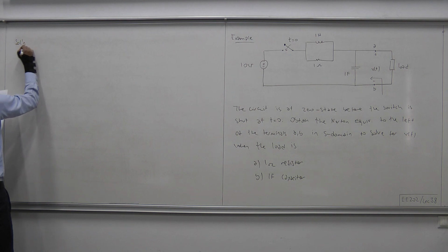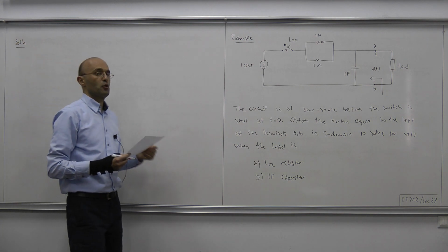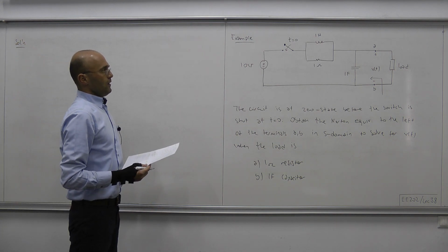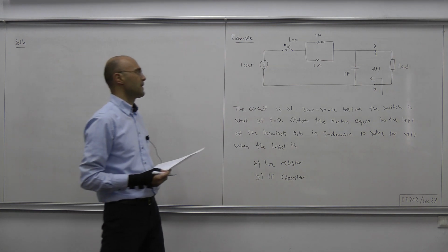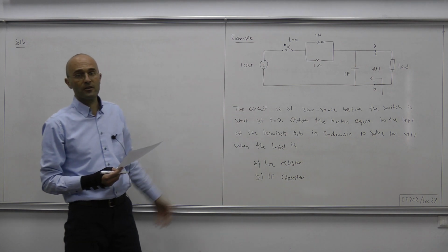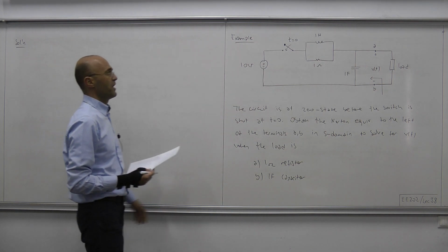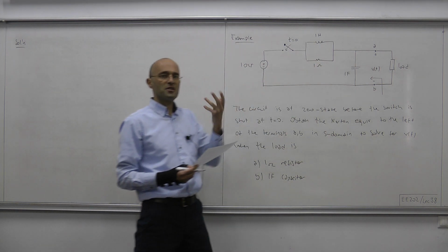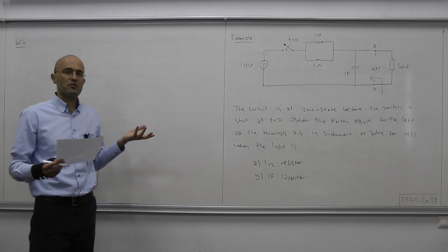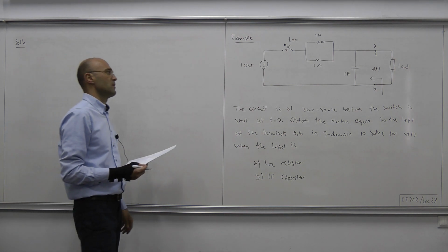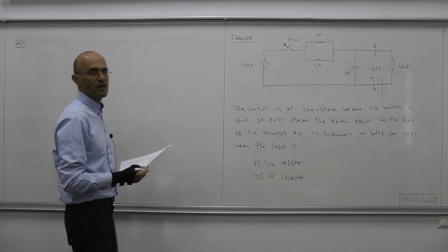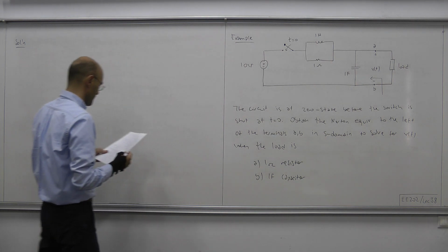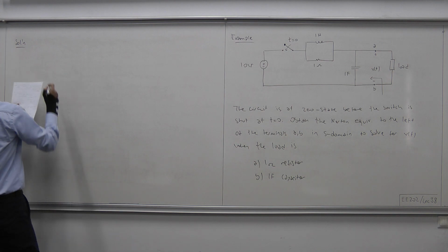Here is the solution. Let's figure out the Norton equivalent seen by the load in S domain. Okay, in time domain we cannot talk about such an equivalence because we have dynamic components. But in S domain, since the circuit is just like an LTI resistor circuit, we can talk about some Thevenin impedance, Norton current, and Thevenin voltage.